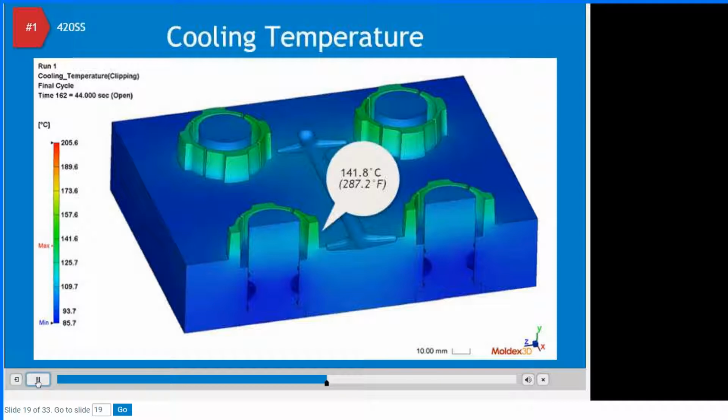and surface appearance challenges. We saw during this animation that when the material comes in, the steel really shows a cyclic temperature behavior, and the highest temperature was right here at these corners of these steel components. This is one core, remember, one core, but there's a cutout here. Right there, right there, right there, right there. 4 cutouts. So the temperature gets the hottest right at these very upper core edges. That's where the temperature is the hottest. And the movie showed this very nicely.